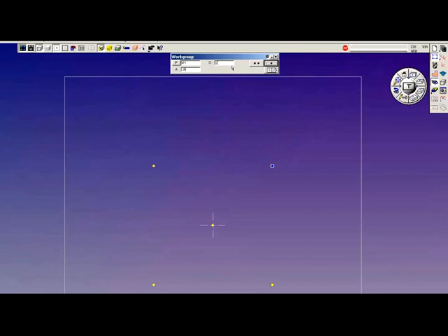The angle of 35 degrees is based on 0 being at 3 o'clock on the clock face. In the counterclockwise direction, we go to 35 degrees, and we click on the single point creation tile, and the point is generated at the correct location.